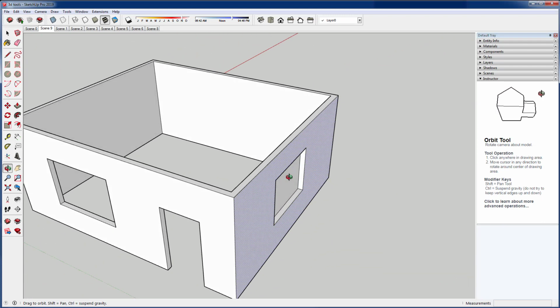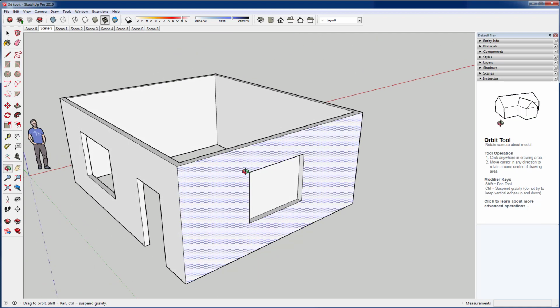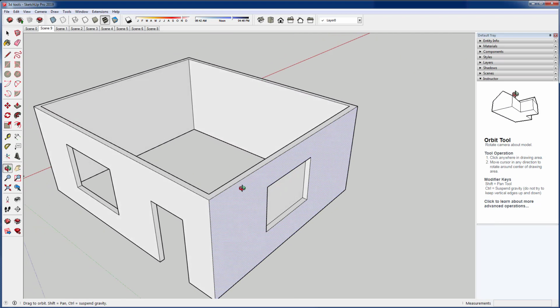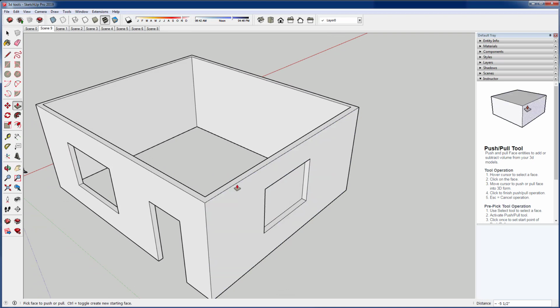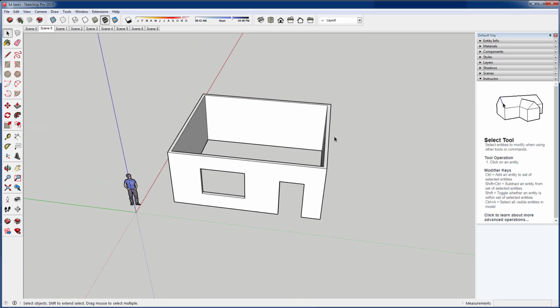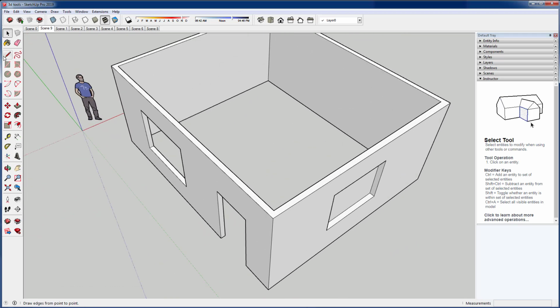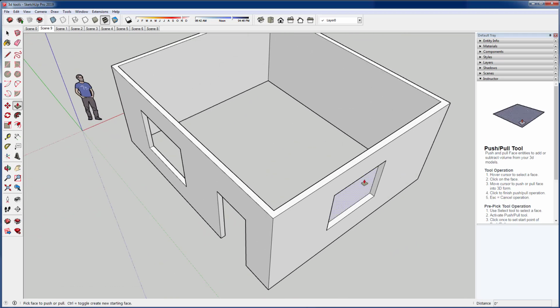So if you find that your holes aren't being cut properly in your object, there's a good chance that the two faces aren't perfectly parallel. So that would usually explain how that could be a problem from time to time. If that happens, then you have to try your best to fix it by, first I would bring that face back out level.